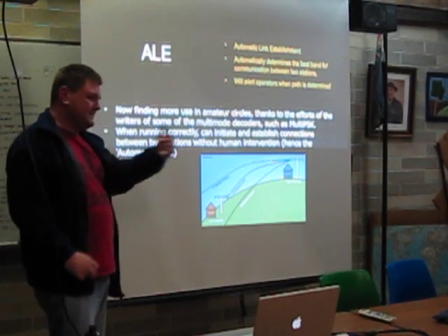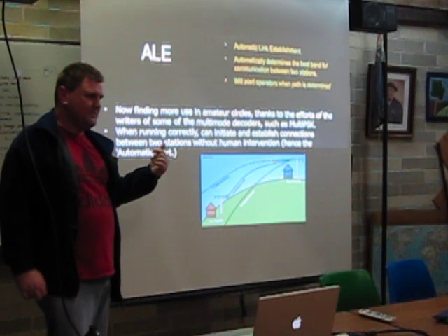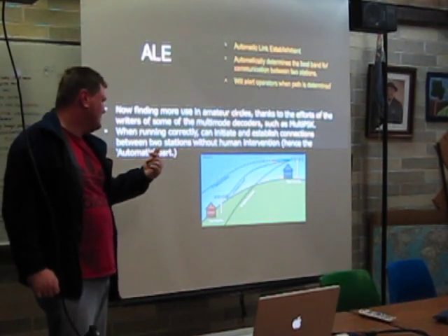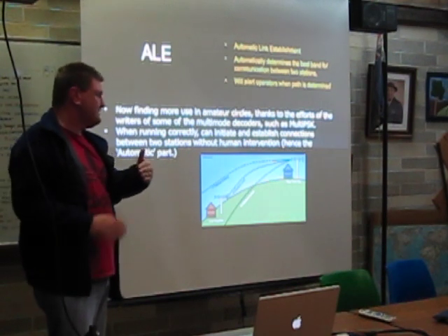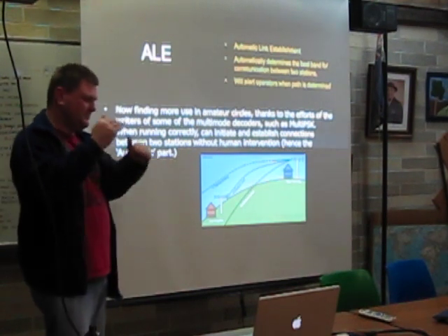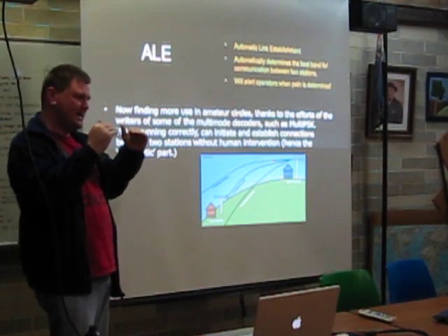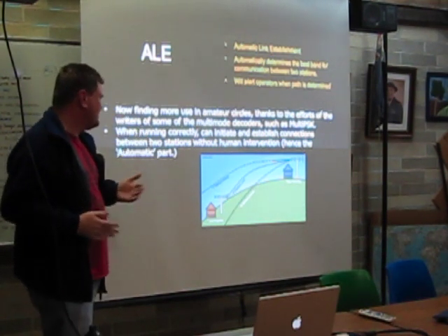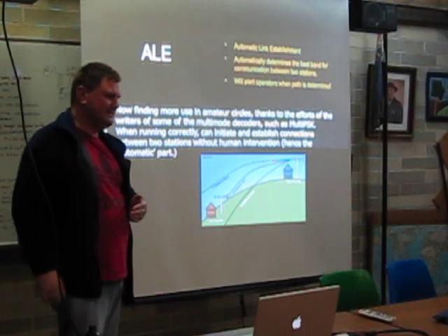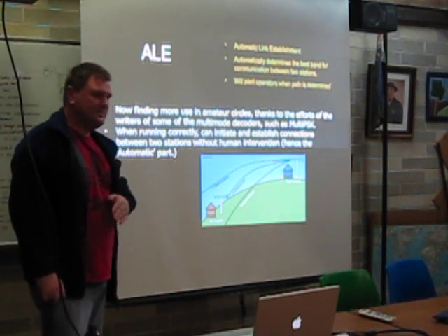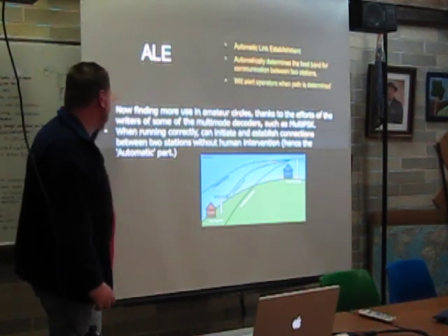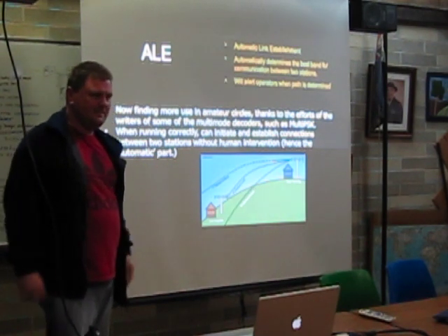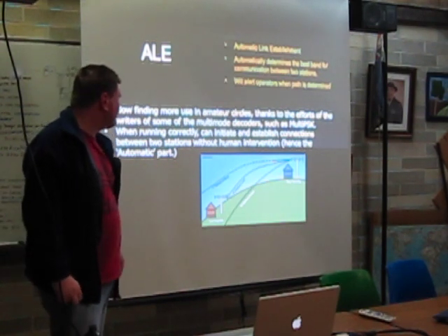And the other station is scanning, and when it hears its own selcall signal being put out, it will respond. This system will try to pick a particular band where it works. If it doesn't work for one band, it'll try a different band. So the person who's operating the radio doesn't need a lot of special knowledge on HF techniques. They let the radios try and find the best communication.